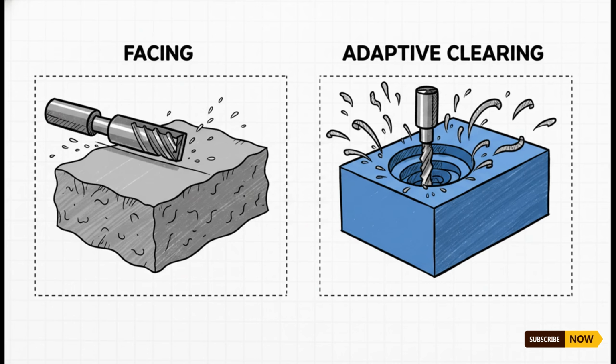During that toolpath generation phase, you're going to rely on a few foundational operations. First up is facing. You see, raw, unmachined stock is almost never perfectly flat. So a facing toolpath simply shaves off the entire top layer to establish a perfectly flat, mathematically true starting plane. From there, you typically move on to adaptive clearing. And actually, this is a brilliant algorithmic dance. The software calculates a highly optimized roughing path that removes the bulk of the unwanted material, but it does so while maintaining a strictly consistent load on the cutting tool. By ensuring that the tool is engaged by exactly the same amount constantly, it prevents those sudden, terrifying spikes in force that could instantly snap your cutting bit.